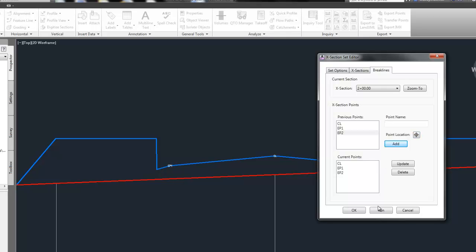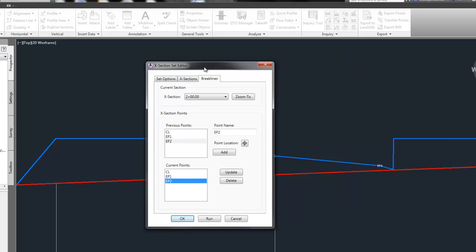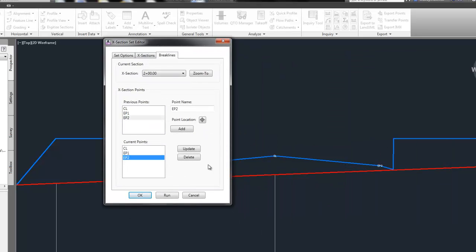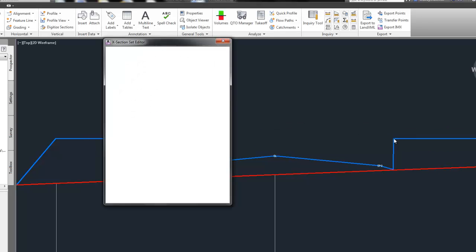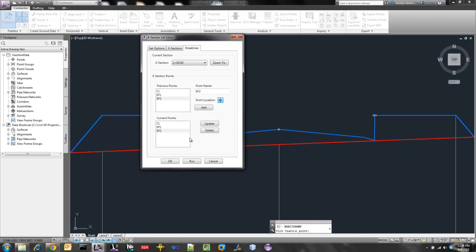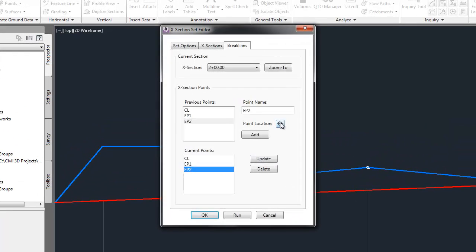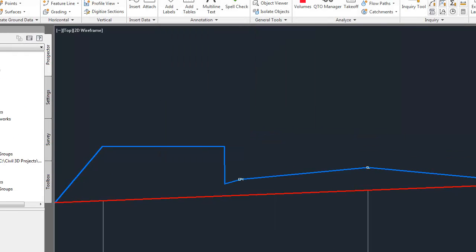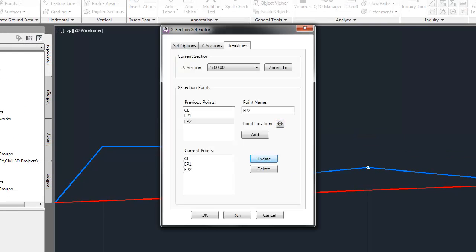And add. If we didn't like where we ended up putting this EP2, so let's say we actually wanted it up here, you can click the point location, click update, and it moves it up there for you. Let's go ahead and move this guy back. So click our EP2, click our point location, click update, and there he's moved back.